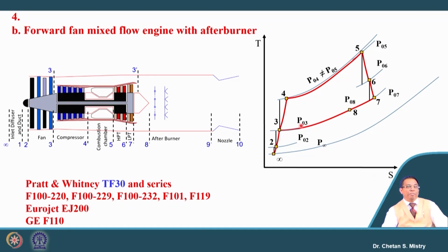It says the pressure from the fan stream and the pressure from the turbine stream, total pressure we are discussing about, need to be the same. So, you can say this is representing nearly constant pressure, and this mixing will lead to a reduction in the temperature. So, it will be attaining some point here, it is point 8. We can say that temperature as T08.